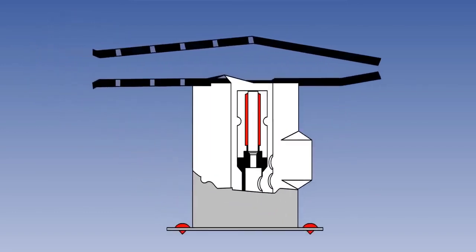Here we can see a diagrammatic cross-section of a total air temperature probe. Let us look at how it works. It can be seen that some of the air entering the probe is turned at right angles to pass over the sensing element. This is to separate the air to be sensed from any water or solid particles present.